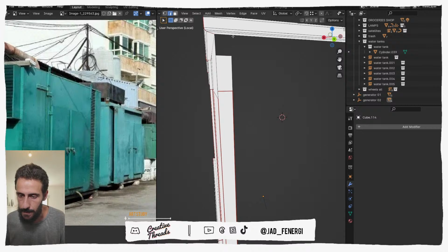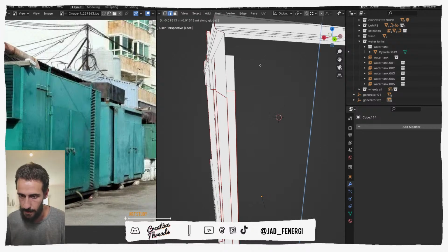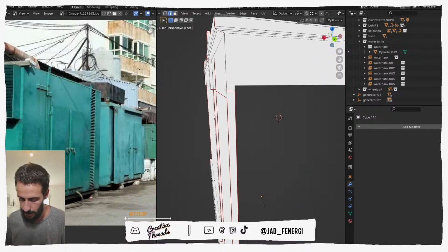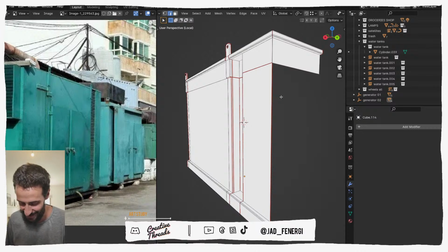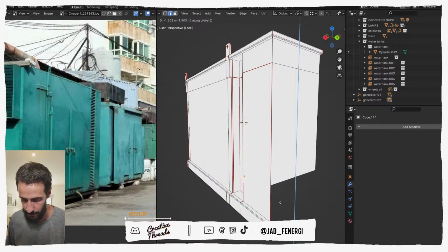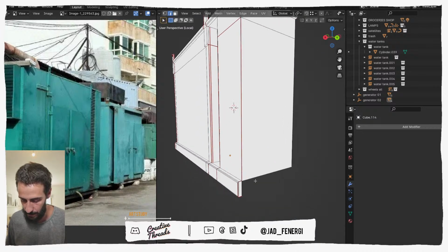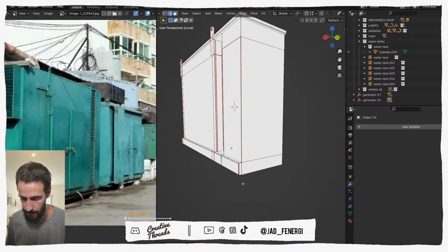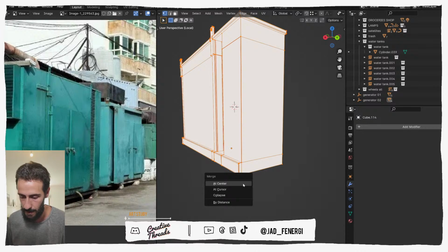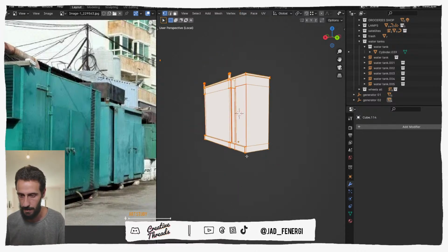So let's press 2, select this, extrude on the Z, G, B from this to this. It's the best way to align stuff. I like this B feature, it's amazing. So extrude on the Z. You can also press Shift Tab, which will snap directly. So E on the Z axis, Shift Tab, and now you can press 1, select everything, press M, and merge by distance, and you merge all the vertices that are remaining.